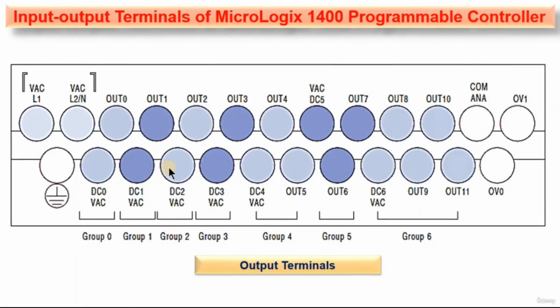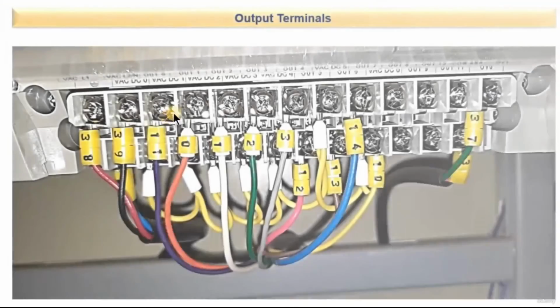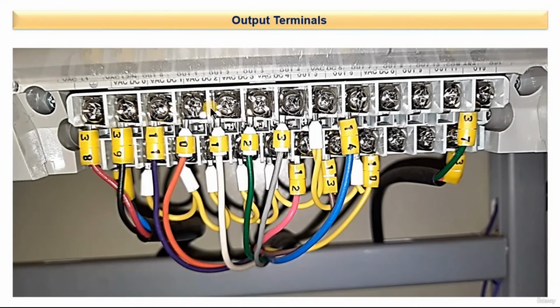Now, just by observing this image, you will get some idea about the connections. Remember, the serial numbers are very important, because if you want to know which field input device you have connected to a particular terminal, this is possible only by using the serial number, right? Here you are observing the serial number 38, the same number which you can observe on the other end of this wire. So there will be no confusion if any fault occurs in the system, and we can simply detect it.